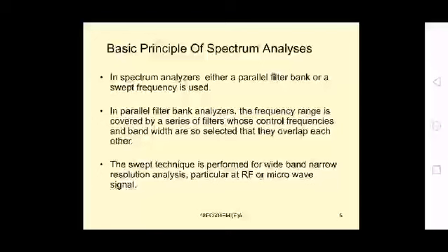So what we are doing is the total frequency range is covered by putting a series of filters whose central frequencies and bandwidth are selected such that they overlap with each other, so that the entire frequency range of your input is covered by this parallel filter bank technique.